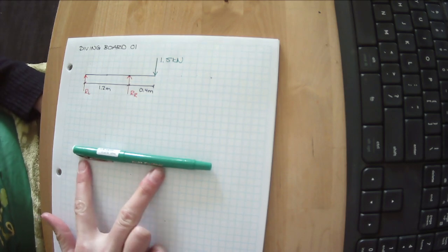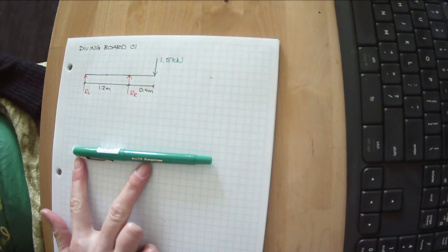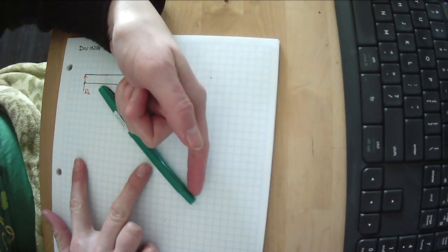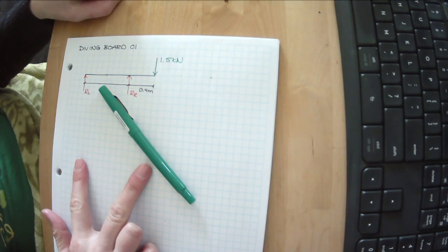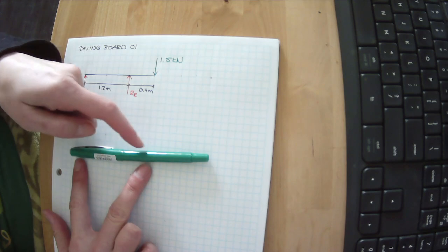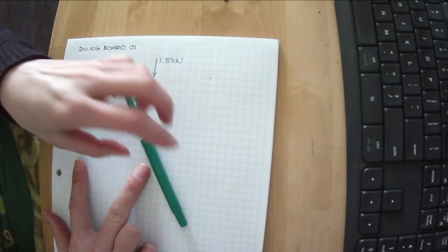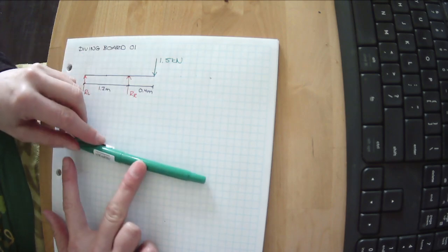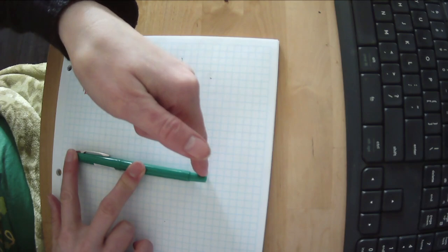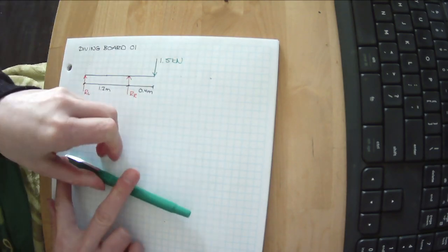If this is my teeter-totter, or my diving board, and I've got 2 supports right here, and I push down on this, this end tries to lift up. This stops it from sinking down into the center of the earth, but this tries to rotate. For this not to rotate, it looks like I need to hold down on this. I need to pull down on this.